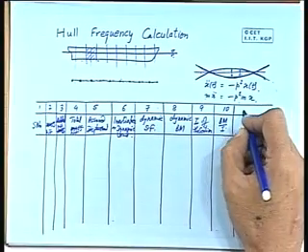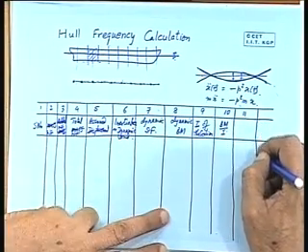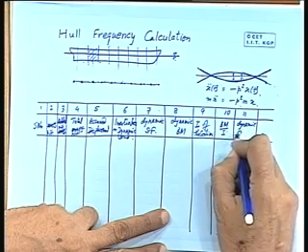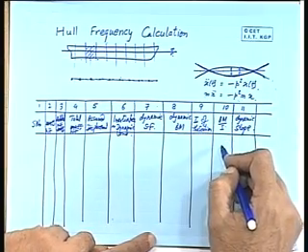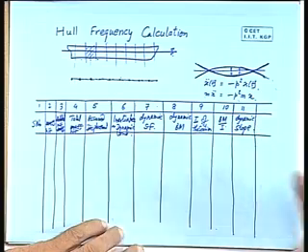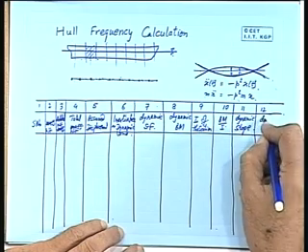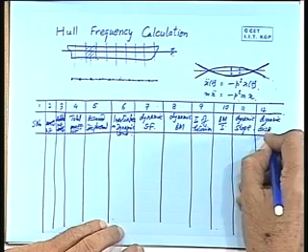Okay? Try to integrate this, you will get the dynamic slope. M by EI, I am not taking E here because E is constant, so why unnecessarily do that calculation, I will do the calculation towards the end. So the M by EI curve is there, integrate it, you will get the slope, and then integrate this, you will get the dynamic displacement. Okay.